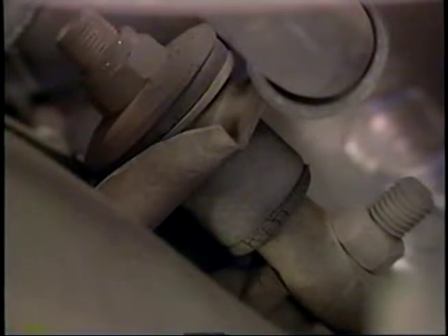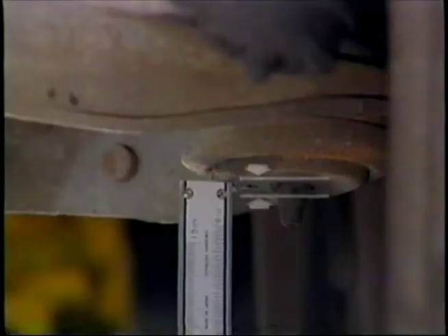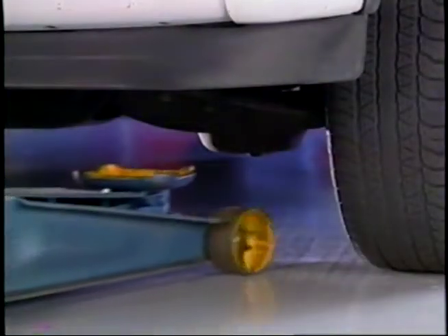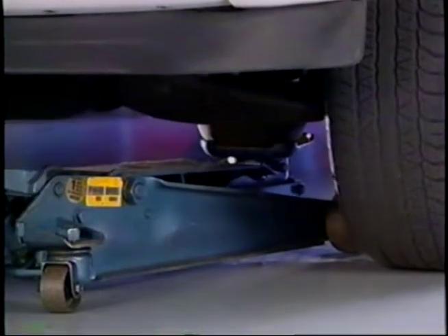If the bushings are okay, look towards the ball joints. Bad ball joints will cause wandering, looseness in the steering, or excessive wheel bounce. Many ball joints have wear indicators that will tell you when they're beyond their usable life. Whenever you work on ball joints, remember to unload the tension on a ball joint before attempting to replace it.